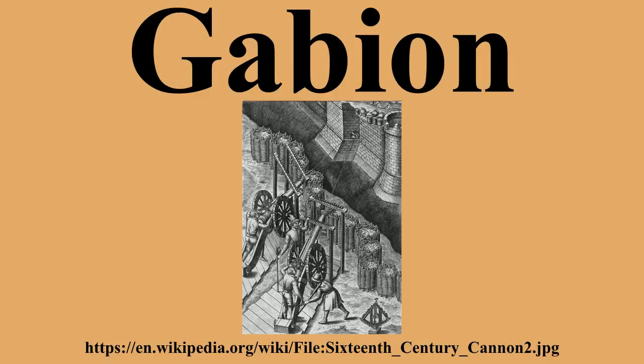Mattress, a form of gabion with relatively small height relative to the lateral dimensions, commonly very wide, for protecting surfaces from wave erosion and similar attack, rather than building or supporting high structures. Trapezium, a form of gabion with a trapezoidal cross-section, designed for stacking to give a face that is sloping rather than stepped. The term is in wide usage, but in contexts related to gabions at least, appears to be a trademark registered by Beta Fence Limited.